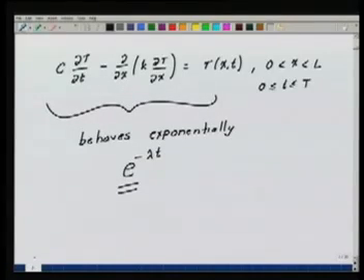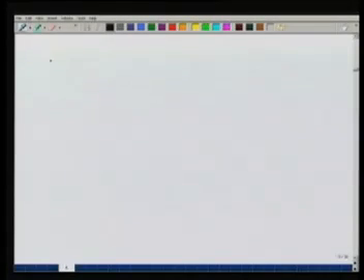Okay. So let's now go and look at first the parabolic problem. If we go back to our parabolic problem, this differential equation, and try to construct a form which can be used in the finite element formulation, what will I do? I will take the instantaneous virtual work or weighted residual formulation.